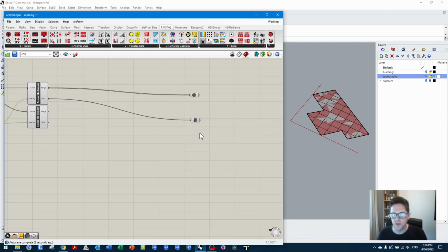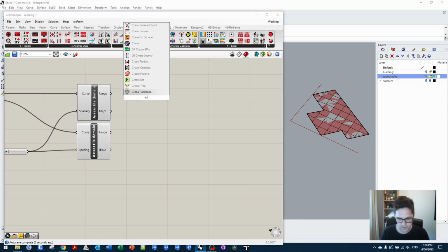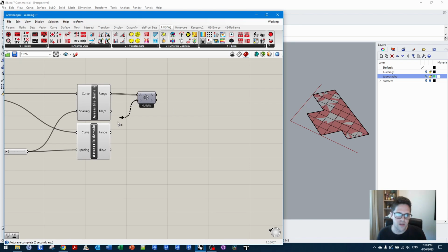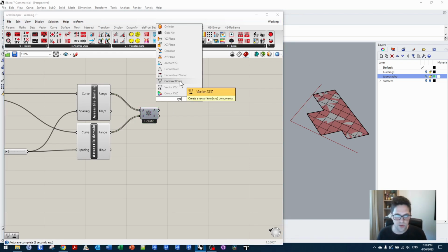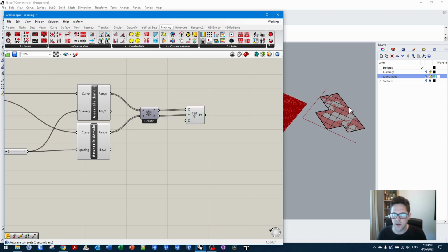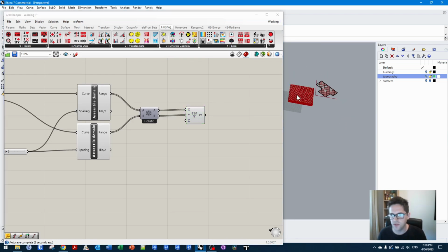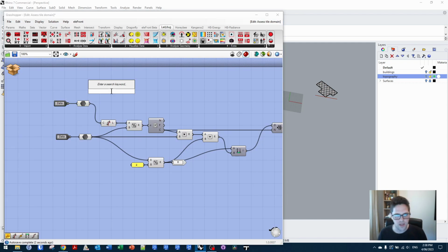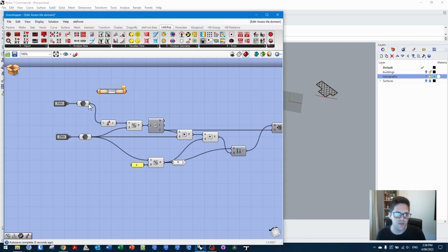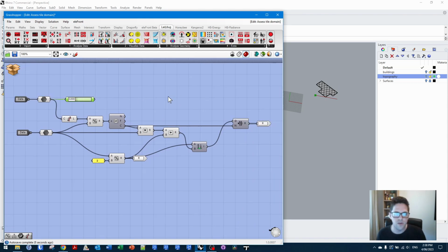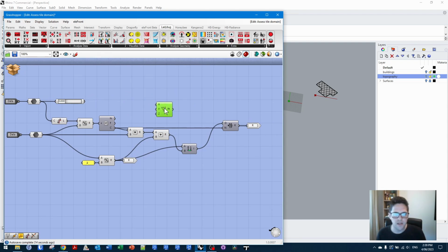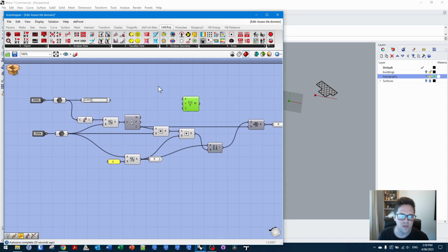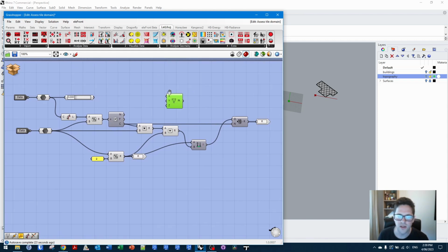You'll pretty much see what this does in a sec, but effectively we can cross-produce these two ranges of X and Y into points X and Y. Now at the moment they're not sitting across the actual surface itself, so we probably do need to modify this cluster to get, in this case, a curve on point, and we're going to get the start point on this curve. And from this, we want to get the X, Y, Z construct point. Now, in this case, we want to firstly get the X point and then the Y point. So that's a little bit difficult, actually. We may need to potentially think about how this cluster is going to work.